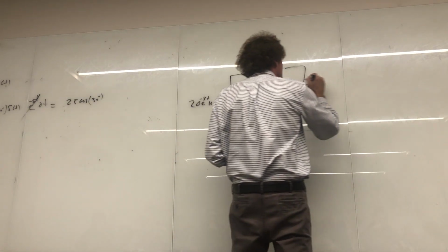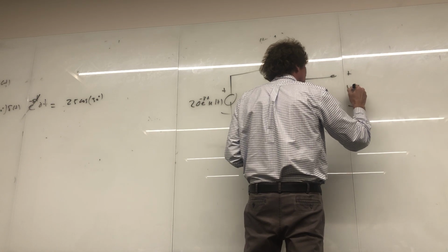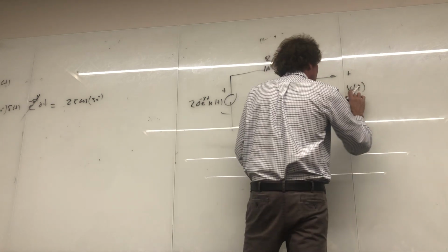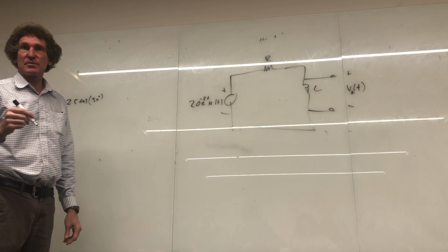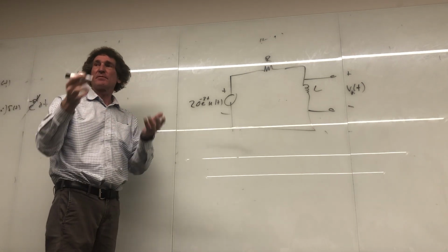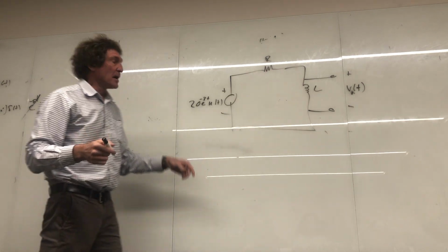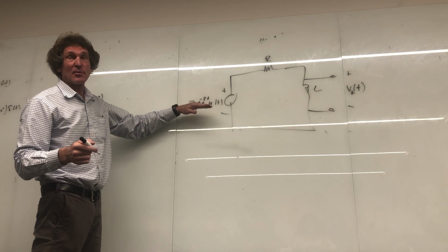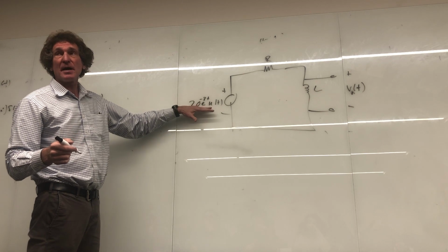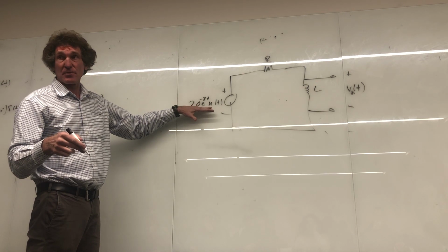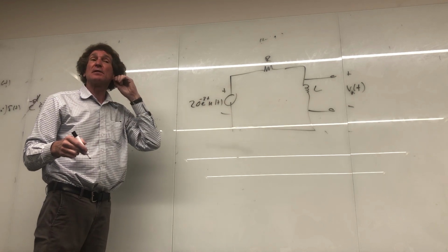Okay, we can do this several ways. We want this voltage, V of t, or I'll call it VL of t. Just V out. We want that. Well, in your past life, the way you did these things was you didn't write differential equations. After you got done with Dave Irwin's class, you said, well, this is just j omega L. We're going to be in the frequency domain, right? This is R. And then this has to be either a cosine or a sine, constant frequency, or a DC source. But you never had this, right? So now what we have to do is write the differential equation first, and then solve the differential equation for that variable by doing a Laplace transform.